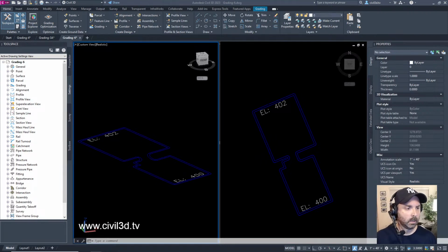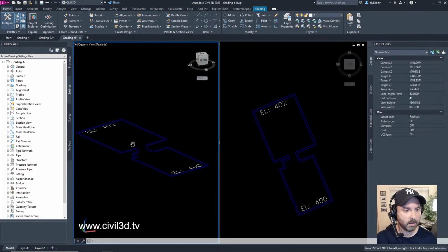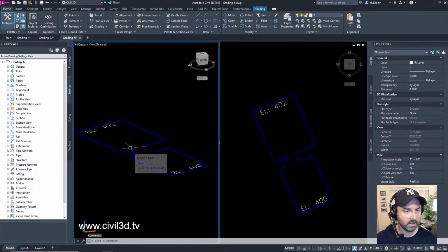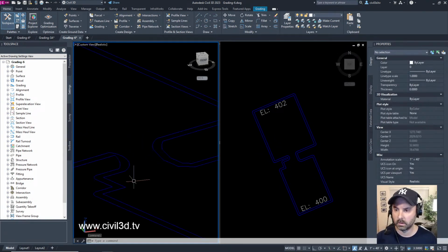Okay. It says right here in my notes, the stepped offset feature line is displayed. Notice that in the left viewport on the left side of the ramp, the curve on the stepped offset feature line is not well formed. See all this stuff? It's not very well formed because it's an independent feature line. You can use the feature line editing tools to refine the solution.